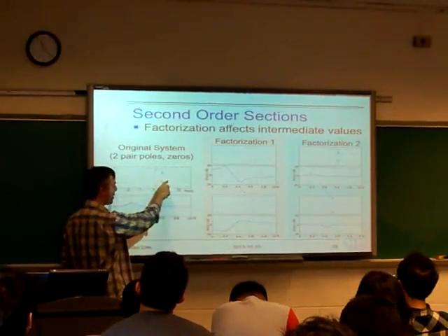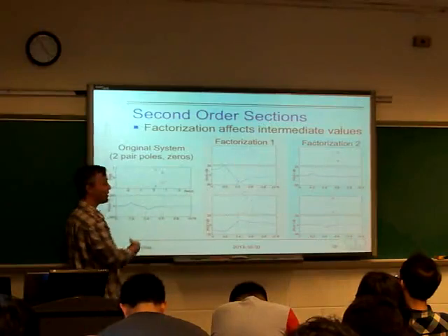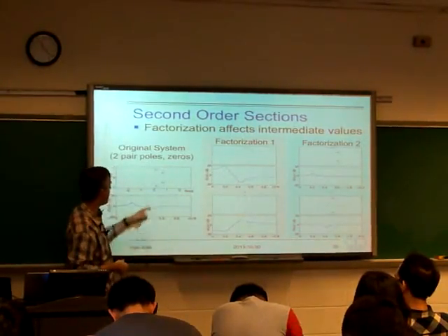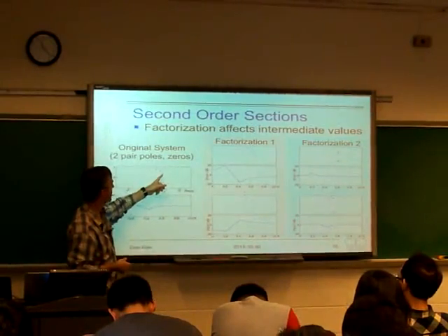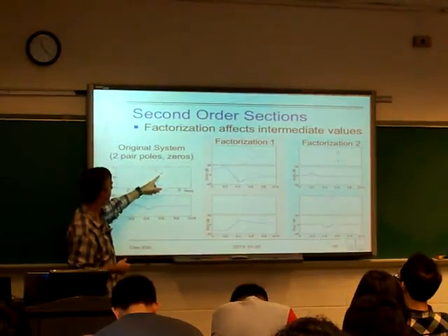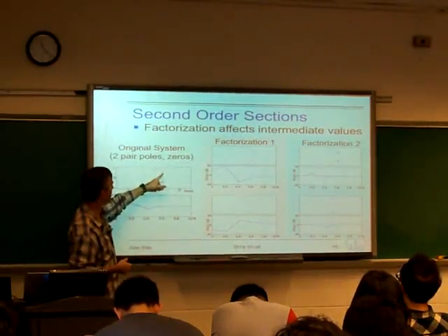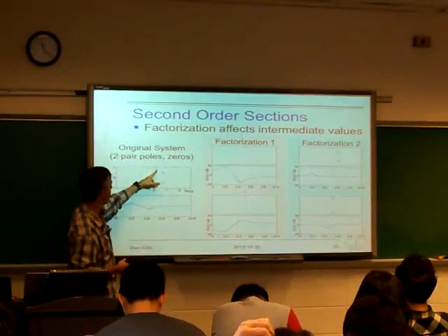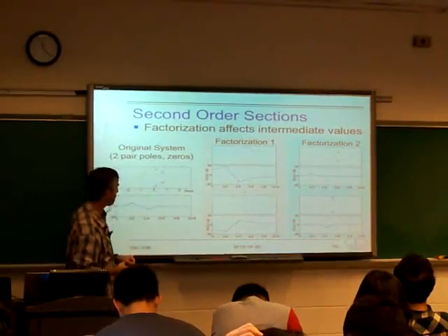If the pole is closer, then it'll be a peak. If the zero is closer, then it'll be a local notch in the frequency response. So here we see there's first a little peak corresponding from this pole, which is for distant frequencies compensated by the zero, and there's a little notch here from the zero, which is otherwise compensated by this pole.